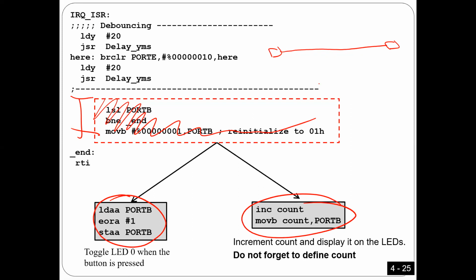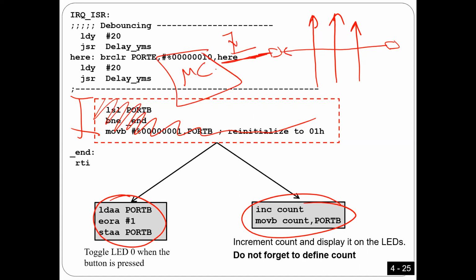And then some cars or some people are crossing the gate, and I want to know how many people entered the store or whatever. So I can have this setting. Every time you cut this line, you make a falling edge, and this one I connect to the microcontroller. Do you understand what I did?